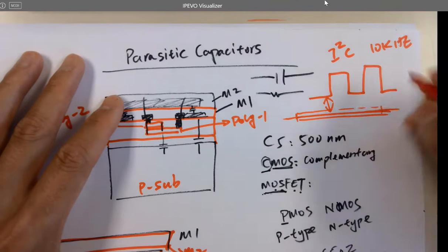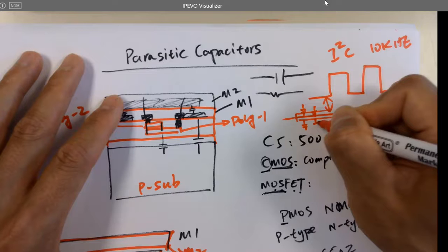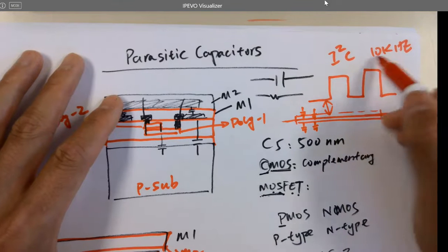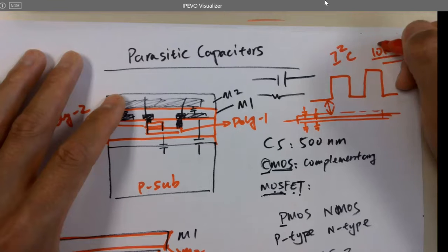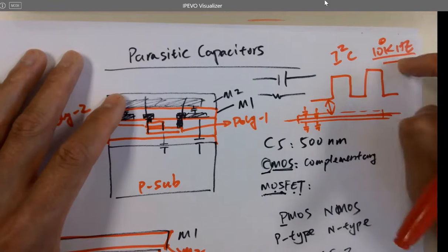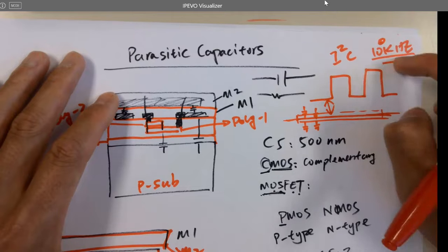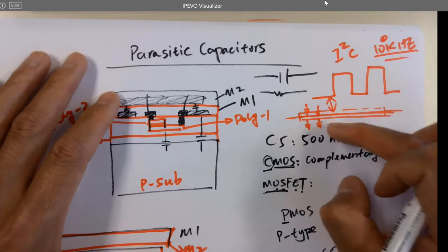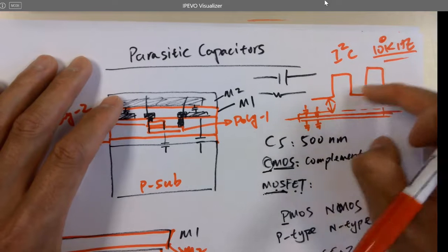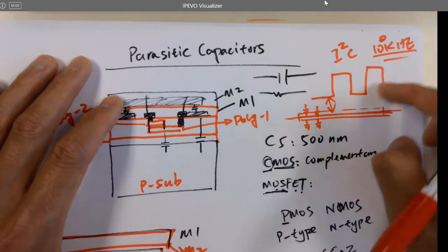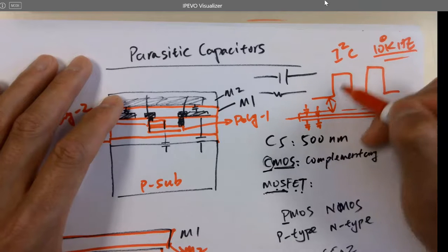So this is a cable, right? It's very long. It has parasitics everywhere. So if you are trying to transmit, 10 kHz is not really high. I think it's probably higher than that, maybe 100K, I forgot. Anyway, it's not very high, but if you have a super long data transmission cable, then you are getting a lot of parasitic capacitance. So it's trying to charge and discharge all these parasitics very fast, which means it's gonna do what for the digital signal?